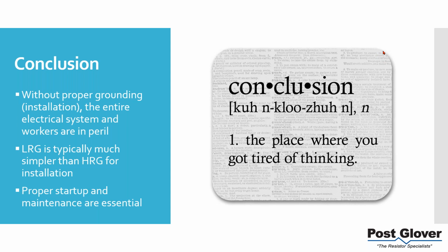In fact, if you are already on a low voltage system, I would recommend you don't have to do a calculation. Typically you would be fine. You might want to add some flexibility with a tappable resistor, and a capacitive charge current measurement wouldn't be bad to go along with that at startup. If you're doing a medium voltage system, I think you have to do a calculation before you even start, because you don't know if you can do it or not.